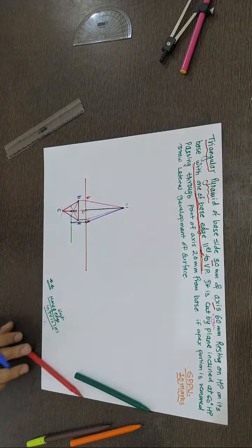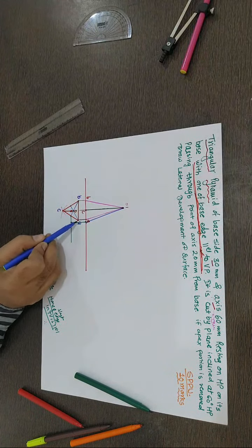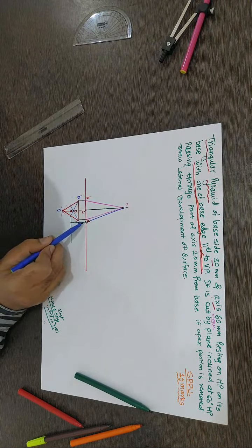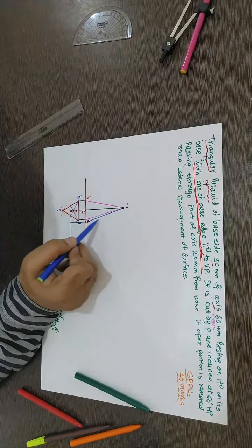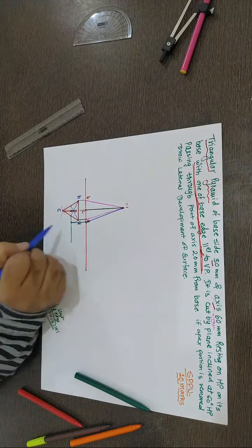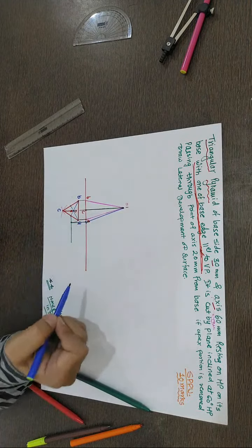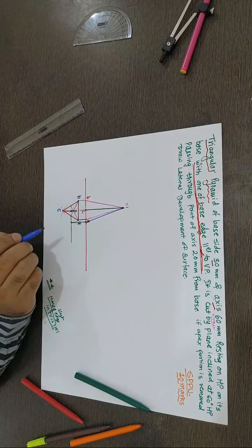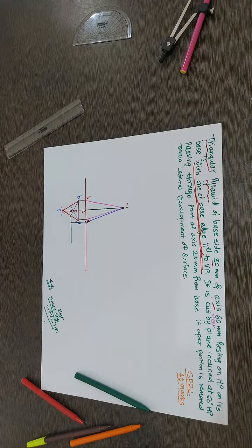So the line which I have drawn right now, by making OA parallel first, take O as a center, A as a radius, mark here up to horizontal, then that point is here and join with O. This line is a true length of slant. That's why in all previous problem we need not to do all this construction, because one edge was already parallel for this. So I hope it's clear why you are doing a construction for this.